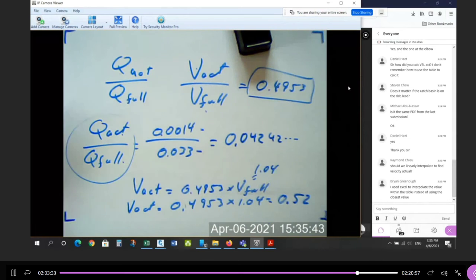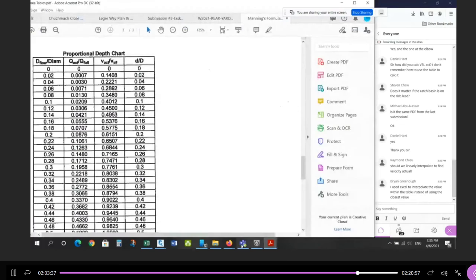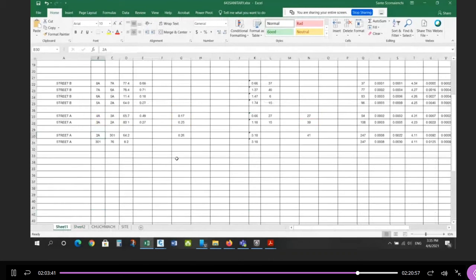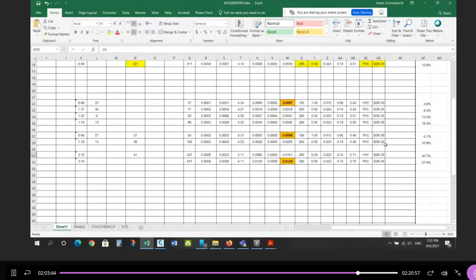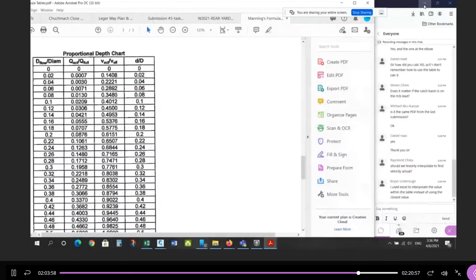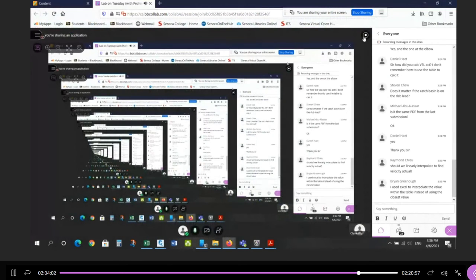It'll be close. You'll notice, though, when you do your sanitary calculations, it's very, very difficult to get 0.6. You don't get past 0.6 until you accumulate quite a bit of flow. So you have to kind of keep that in mind. All right, any other questions?